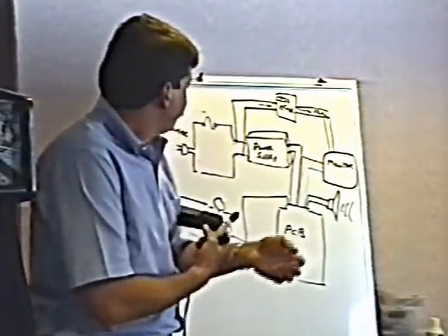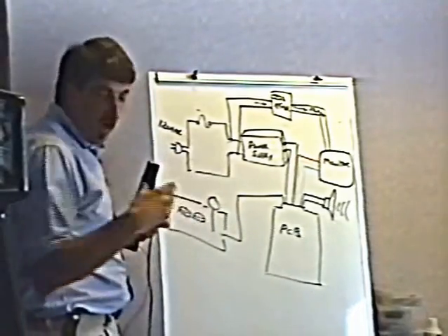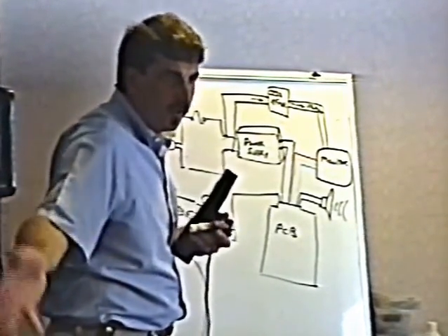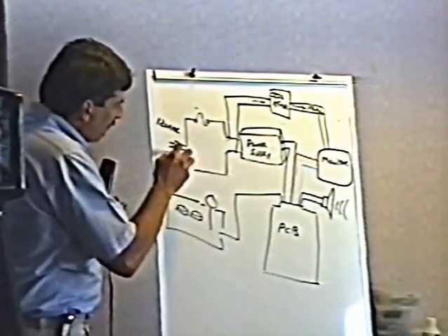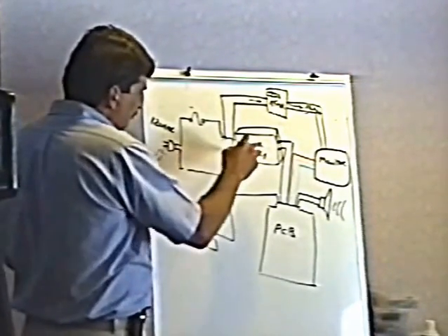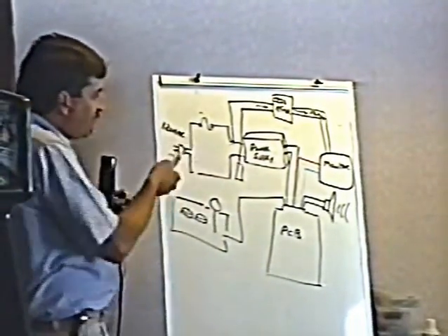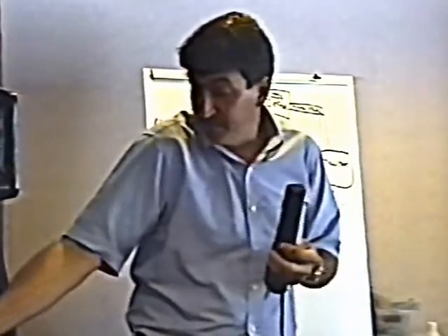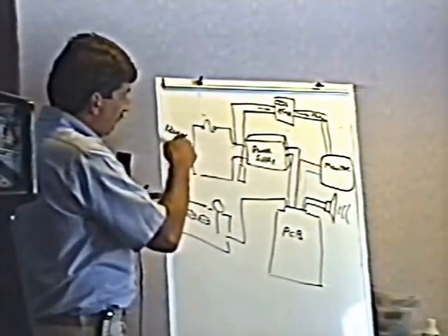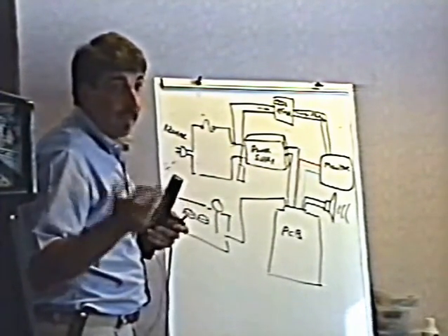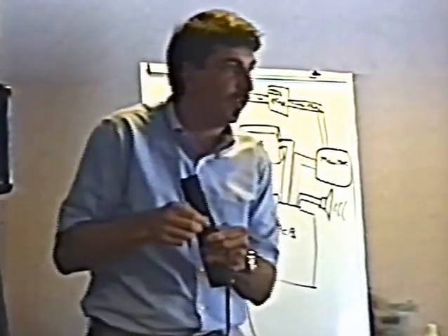Next step then is, with this thing out, disconnected, in my hand, not plugged into the wall, I use my meter on the ohms scale, the continuity scale, like the 200 ohm scale or whatever beeps on your meter. I start by putting one meter lead on one of the prongs and the other meter lead on one of the wires here, or I put one meter lead on a wire here and then just try each of the two prongs. What I'm checking for there is continuity. In this case, when I put one meter lead here and one meter lead on this top prong, it beeps. That wire's good, but when I move to the other one I don't get a beep. One of the wires is broken, and it's really probably the plug.